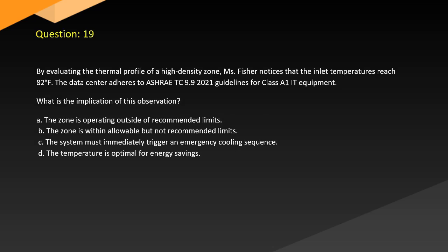Question 19. By evaluating the thermal profile of a high-density zone, Fisher notices that the inlet temperatures reach 80 degrees Fahrenheit. The data center adheres to ASHRAE TC 9.9 2021 guidelines for Class A1 equipment. What is the implication of this observation?